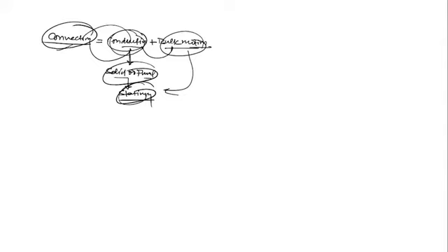So convection is not a phenomenon. Convection is simply conduction along with bulk motion. When the bulk motion is absent, we should not say convection, because convection comes into the picture only when the fluid is in motion. Clear, beta? Or in other words, you can also say convection is conduction plus advection. What is advection? Do you know?